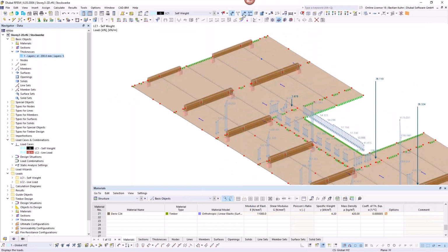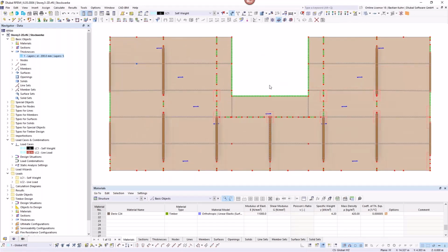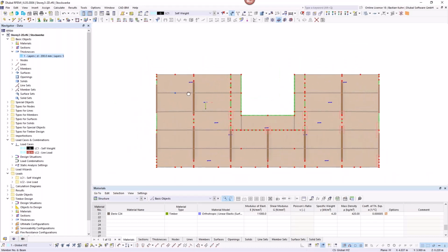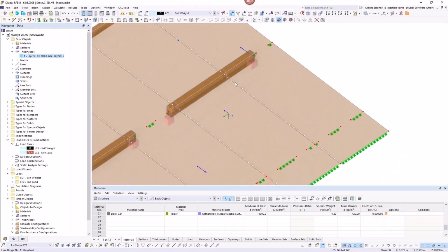But now when I'm working as a designer and constructing it, you probably realized already the blue arrows here. It was in previous versions always hard to know how I'm assigning the plates. If we look at the downstand beams that I have underneath those plates in here, you see that there's a downstand beam that is supporting this plate and this plate and this.